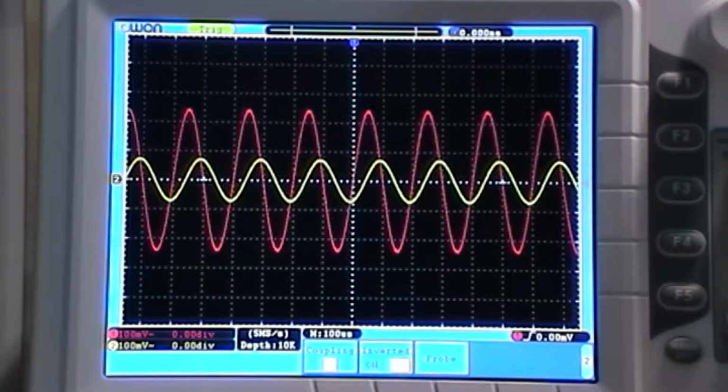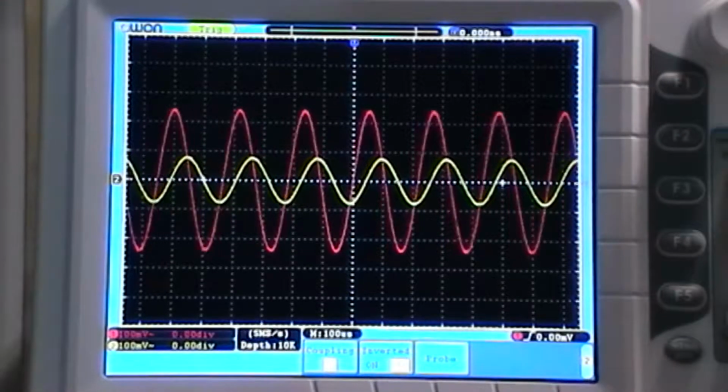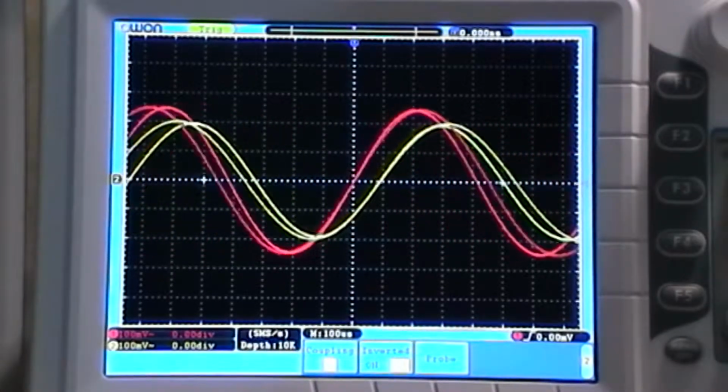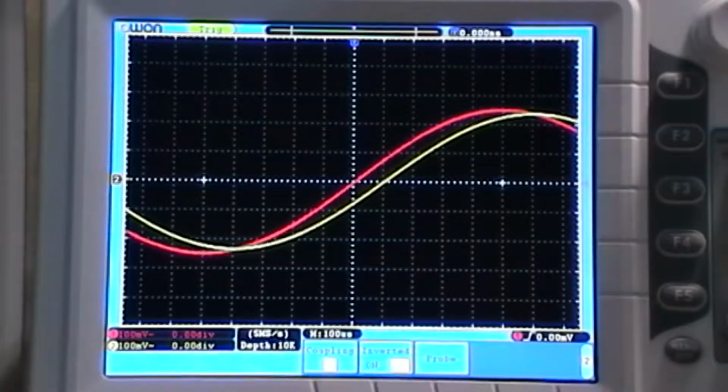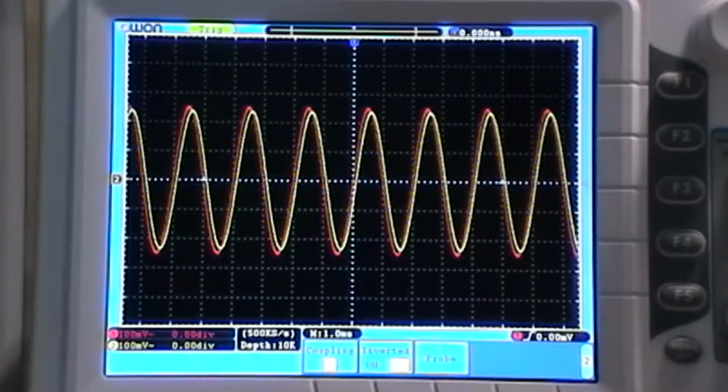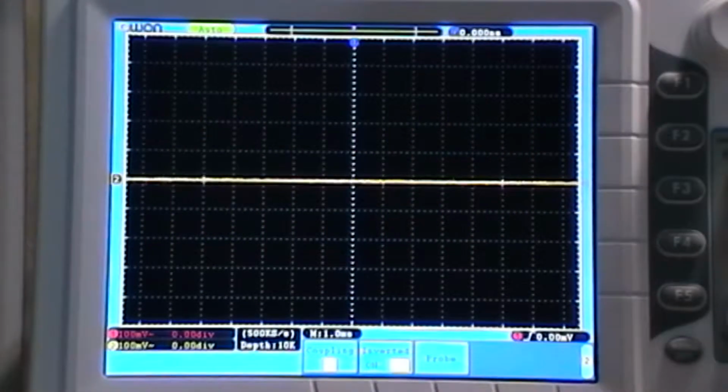So effectively, as this is a low pass filter, the lower the frequency, the more that frequency is going to come through. So if I take this back down to 500 hertz, I'm getting pretty much all of that frequency. So let's change that out to a higher capacitance, and I'm going to see if that increases or reduces the point at which it starts to attenuate my signal. So let's turn that channel off.